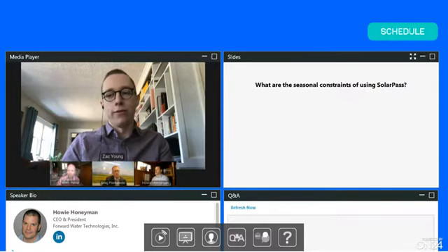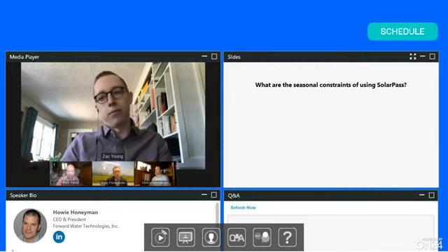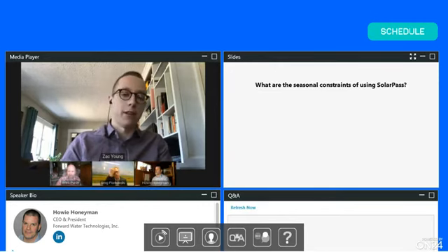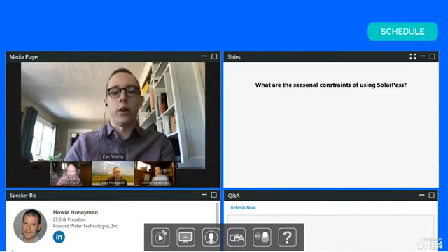So where you have lower UV intensity or fewer hours of sunlight a day, it would affect the overall throughput of the system, though we find that the process is pretty well aligned with the received UV, and so you turn up and turn down appropriately. And in fact, that's a part of our process design as well, being able to monitor, predict, and confirm the requisite dose of UV as we go through the process on a day-to-day, week-to-week, and seasonal basis.